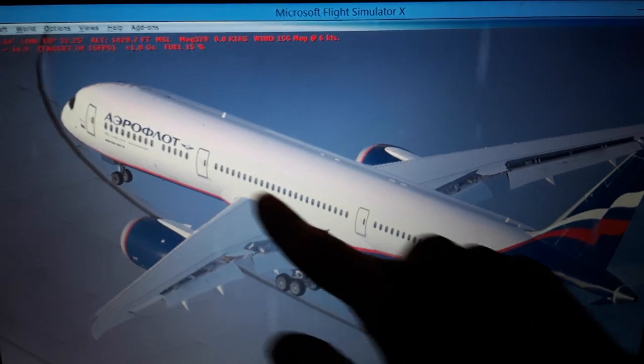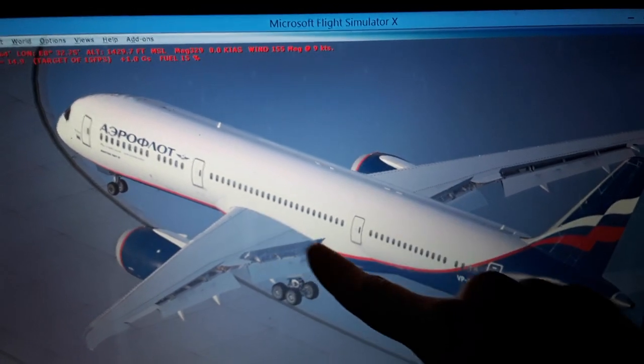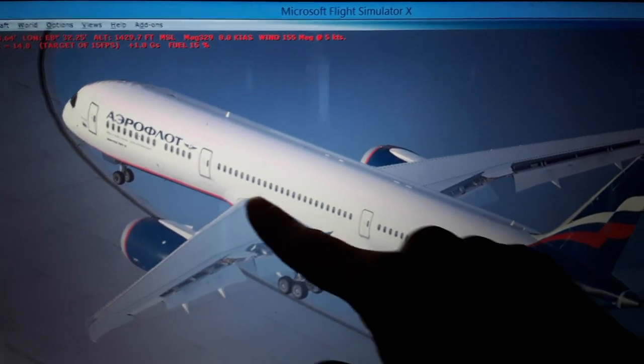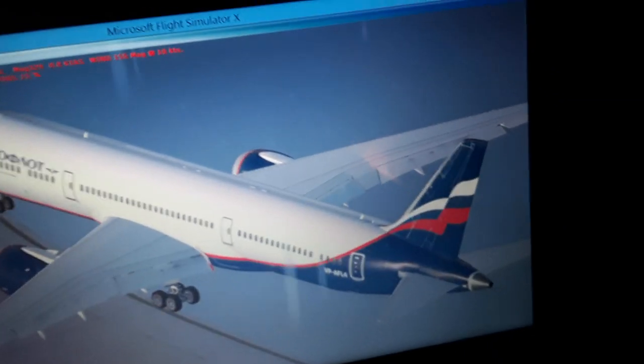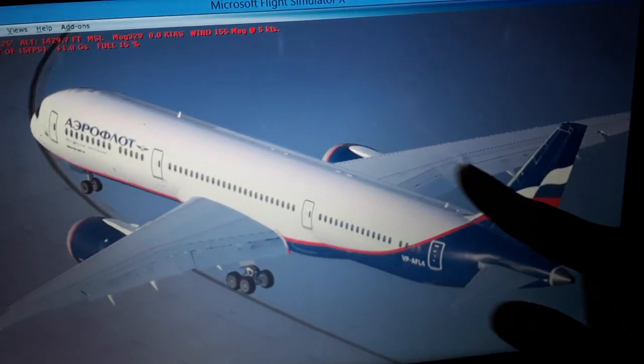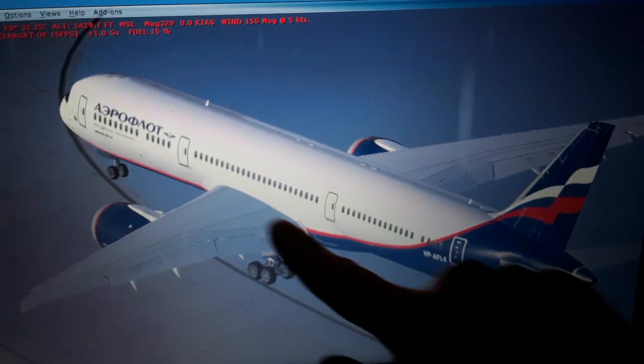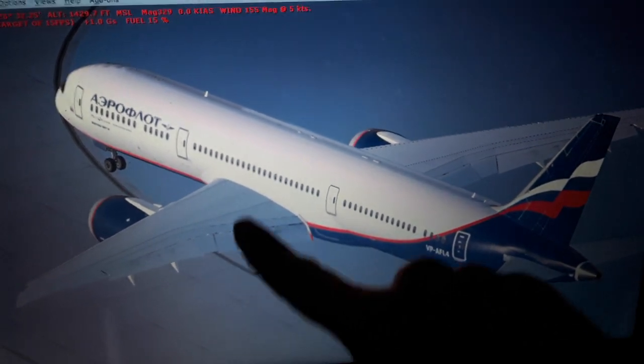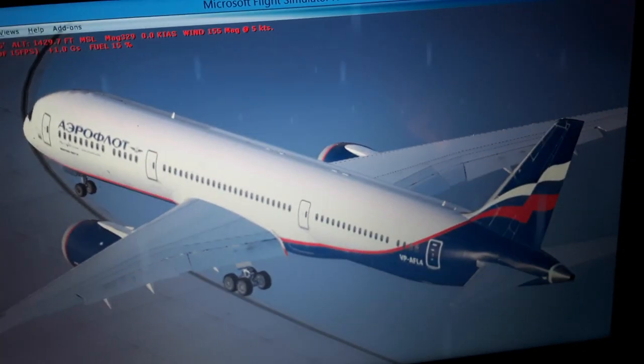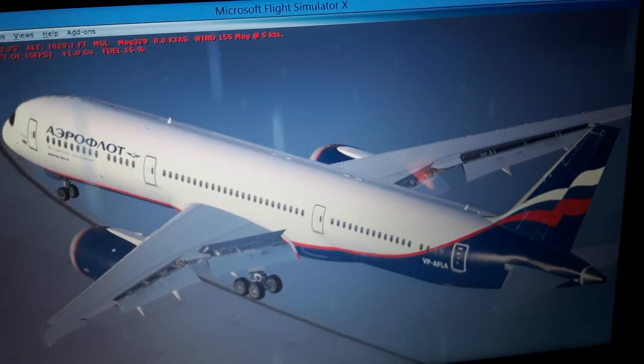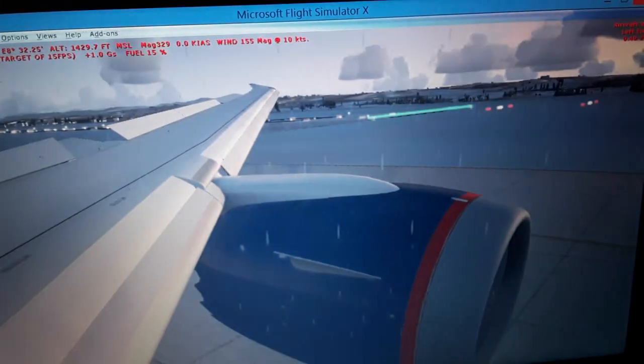Also in the top surface of the wings we have the center of pressure, moves back and forth, and also the airflow becomes detached as we fly for a given angle of attack and airspeed that increase or decrease. So we have the stall of the wings. When we fly, the airflow becomes detached and makes the aircraft fall from the sky.